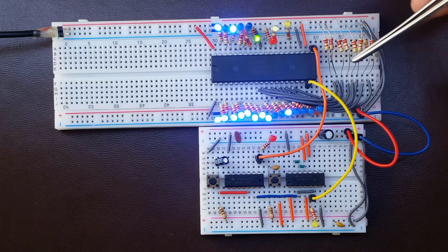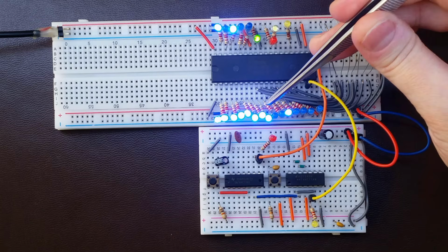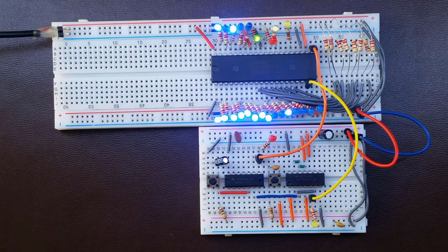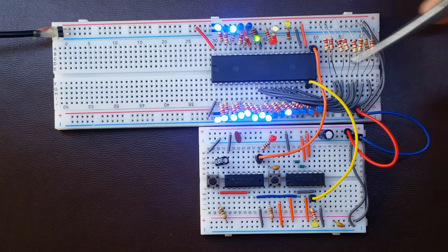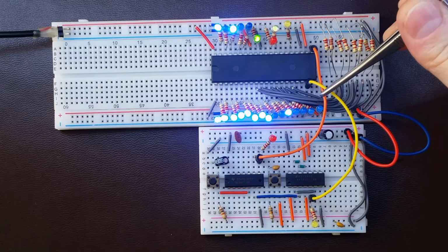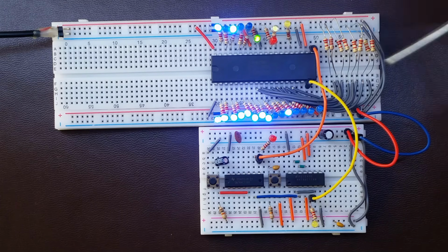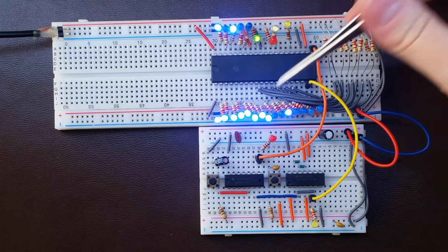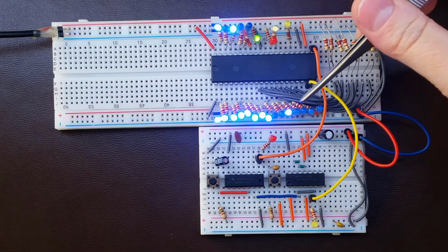But look what happened to the 8 least significant bits, which are, remember, shared between address and data. Currently, in the second cycle of the 4 cycles of the bus transfer, these are data lines. And as you can see, our resistors pulled the 8 bits up or down according to what we wanted to achieve. We wanted the NOP machine code, which is 1001 and then 4 zeros.